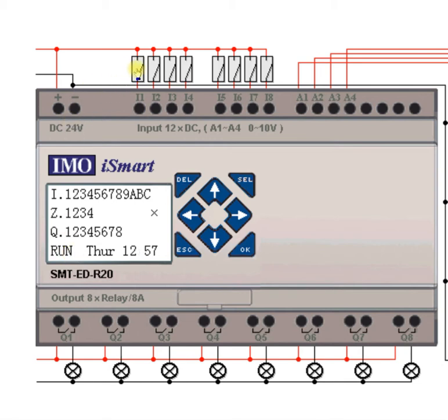Now, if we tell it that a material switch is on, then it's going to start the loading process. After a slight buffering, you can see the motor's on, station 1 is on, and it's activating the proportioning valve appropriately. When it's done with that, it's going to clean the filter, which is what it's doing now. The T-valve is still open so that it can clean the filter, and then it's going to try to load again. And it will keep doing that unless you put on another station or the material switch stops calling for material. So that's how it works.